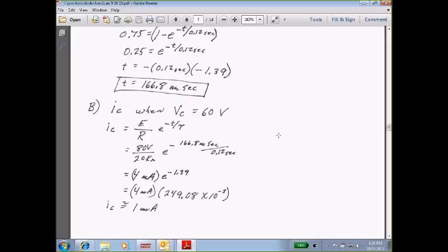Then I have the students do a little lab, and what we do is we take just a 6-volt incandescent light, just a little small lamp, and we hook up a power supply, and I put a cap in there, and I put a small resistor in series with it, and I have them apply a DC voltage to it. Actually, they're using a 9-volt battery. That's the purpose of the resistor. And I have them put a push-button switch in there.